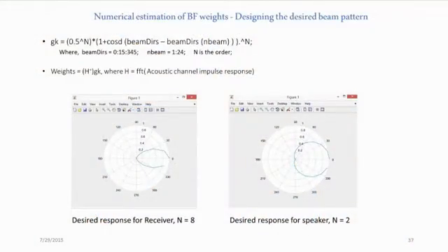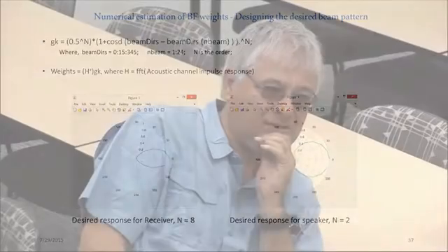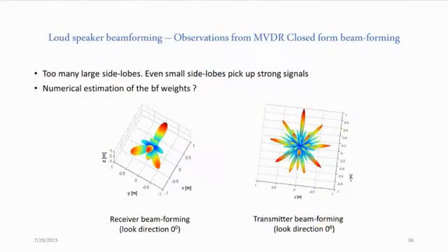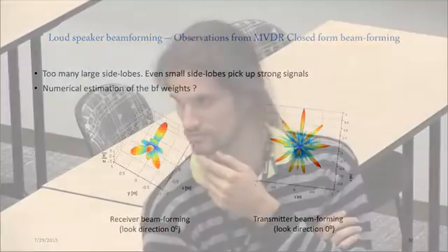So back to the beamformer synthesis for both the loudspeaker array and the microphone array. Did you use the phase information? Did you get any phase information, or was it complete noise? Yes, so the beam matching actually uses both phase and magnitude. But the question is whether we should perhaps ignore the phase in some regions rather than use it for the whole 360 degrees. I mean the phase response of the transducers.